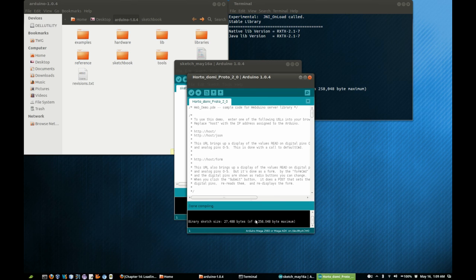If you have a problem right here, then you want to make sure that all the steps were properly done before this, mainly the step where you're adding the Webduino code, because if the Webduino code's not in the libraries folder properly, that's where this thing may hiccup because it can't find something, like the server implementation or something like that.